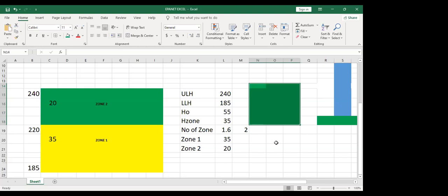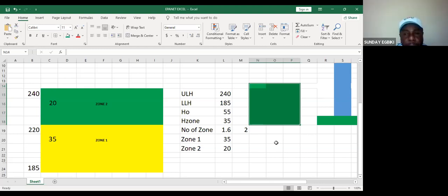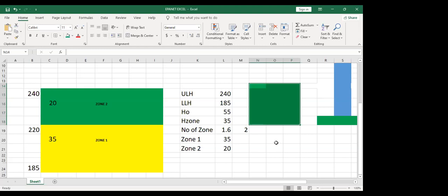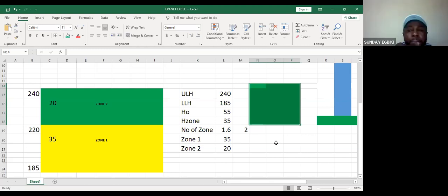Or do I get it wrong? And then I look basically for a point in my area where my tower is not 10 or 20 meters high, only like 6 meters, as low as economical as possible. But the outlet of the tank should be 2 bar above the upper limit of each zone, isn't it?